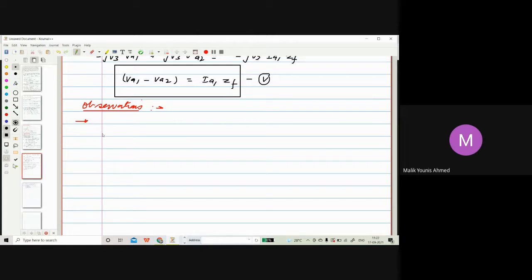Nice. So number 1, from the above equations, in case of line-to-line fault, the zero sequence component of the current is absent. So that is fine. And the positive sequence component of the current is equal in magnitude but opposite in phase to the negative sequence component of current.